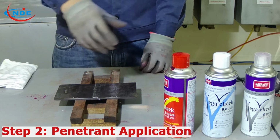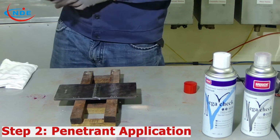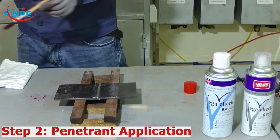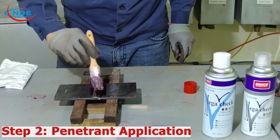Step 2. Penetrant application. We can spray or brush penetrant to apply on the surface of the testing object.